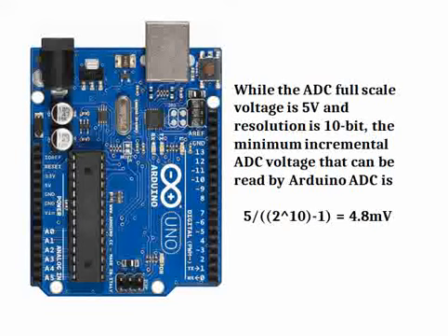That means if a microcontroller reads 0 volts now, there should be a minimal incremental voltage which can only be read considering the resolution. So that minimal voltage is nothing but 4.8 millivolts. So 2.7 millivolts of input is still treated as 0 by Arduino Uno.